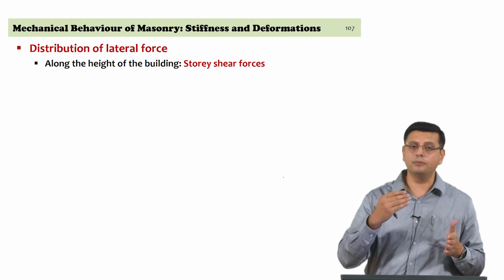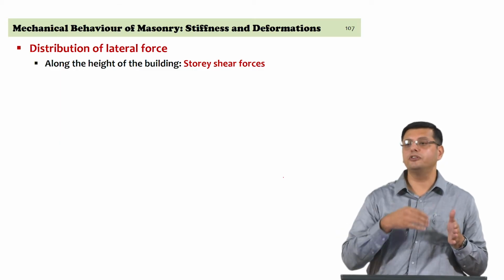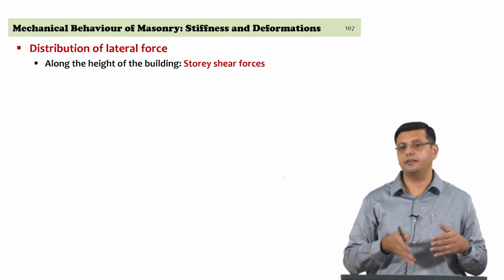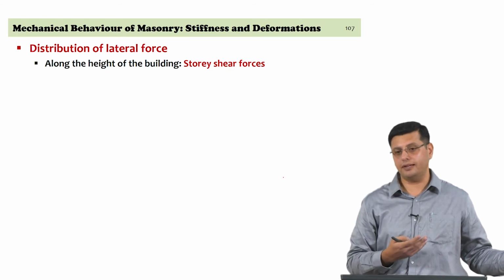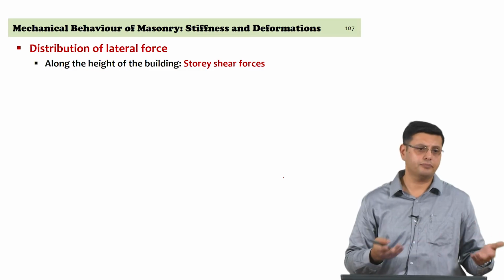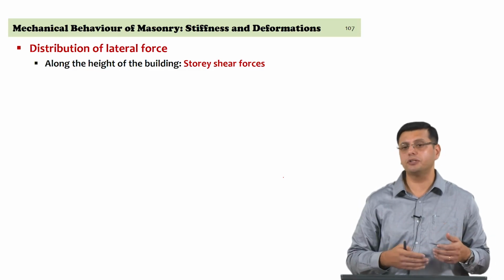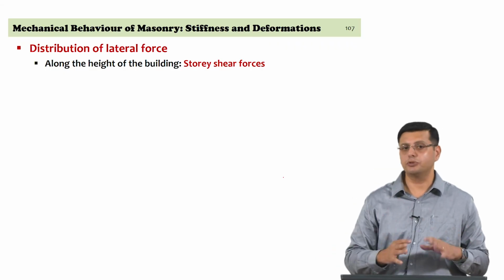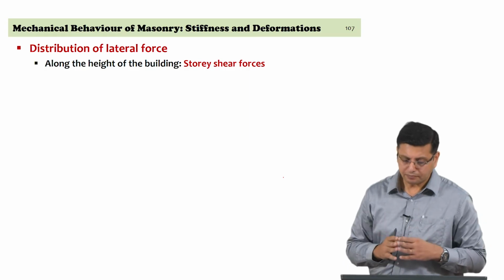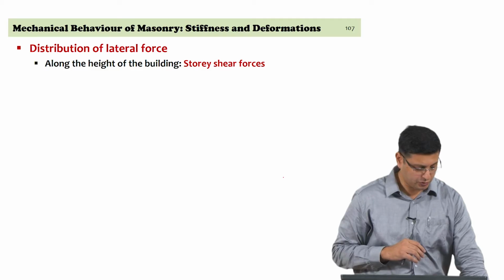But if you have multiple floors, then the story shear, the shear force corresponding to each story, has to be estimated from the overall base shear, and that depends on a certain distribution that you will assume along the height. Codes give us simplified ways of doing this. You can assume a triangular distribution along the height, you can use mode shapes to do that distribution, but that is one aspect that we will start examining when we do actual seismic design.